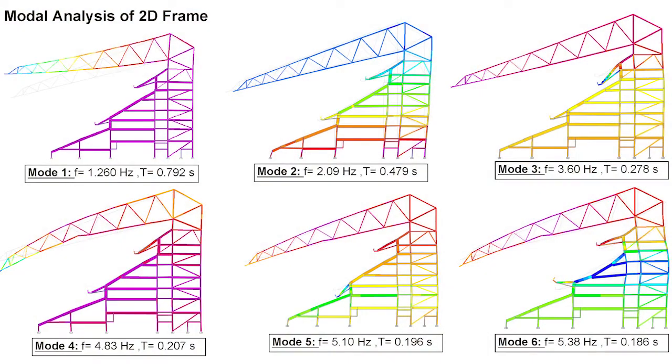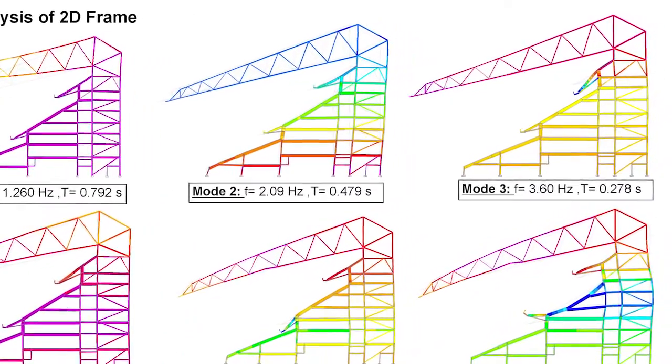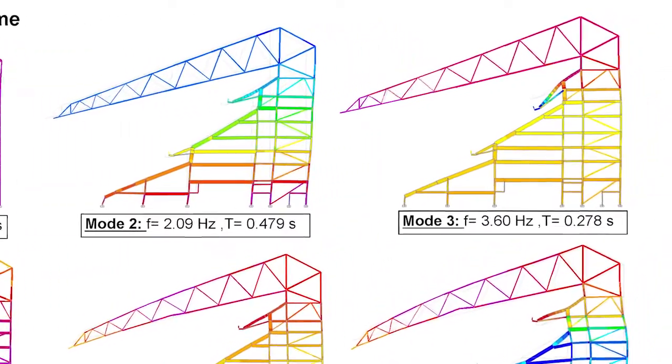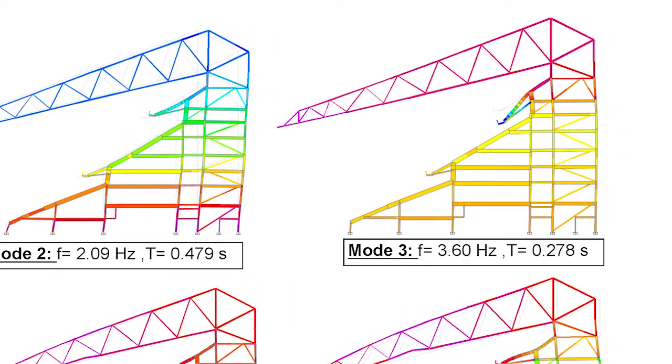An example we've done is for a Premier League club, who were asking if they can host concerts during the off-season period. What we did is we started with a 2D analysis of the stand to realize which mode could be excited by the crowd. And then we found that the 3rd mode is the one that could be excited by the crowd, but it has a frequency which is much less than 6 Hz. It has a frequency of about 3.5 Hz. And that meant that we had to go through the complex dynamic analysis of the structure.